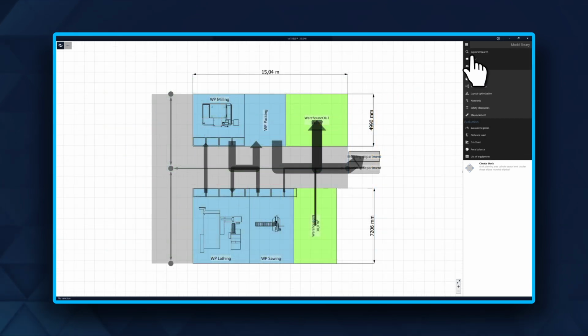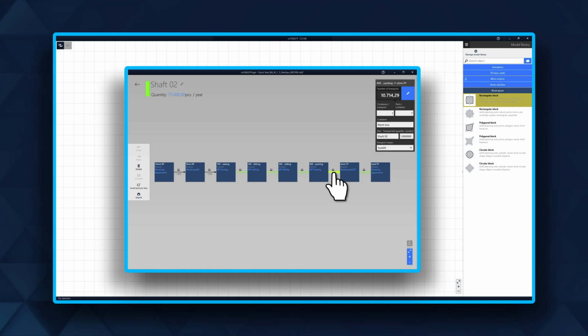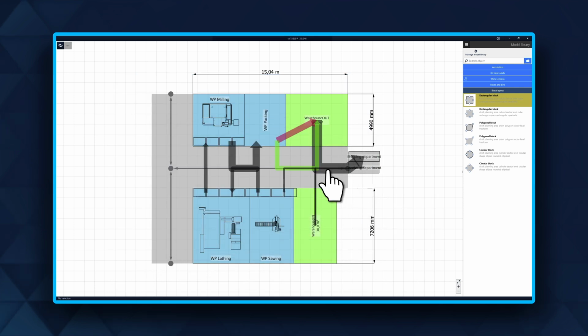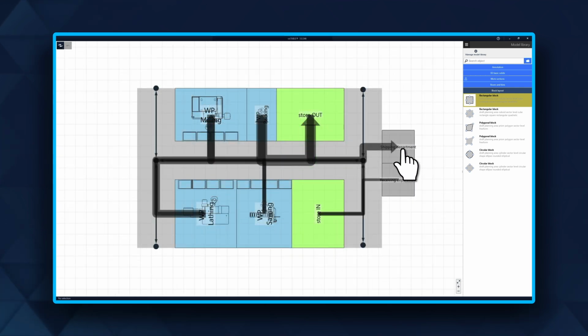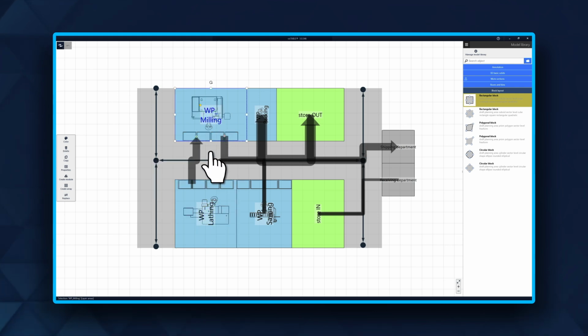Important exceptions. Transport means like worker, direct, or gantry crane completely ignore transport networks. Trying to force them onto paths will not work. Routing through the network happens in two clear steps. First, the system snaps from the source or the sink to the nearest usable transport network edge. Then it calculates the shortest path throughout the network. In certain cases, adjust connection points of sources and sinks to prevent inefficient routing paths through your network.